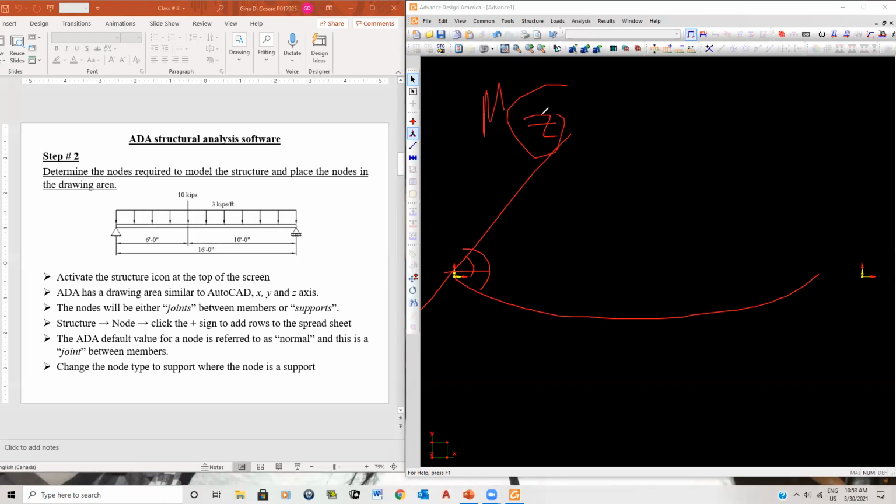If you were doing a three-dimensional analysis, then when you're in the other axis, you have to free it about the MX and the MY. Otherwise, if you leave those fixed, it will not change anything in your analysis. But to make sure that you've done it properly, you have to free it on the MZ, and that's why you still have the red dot. And I'm glad you had that mistake. That's a classic mistake everybody makes. They always use the wrong axes about which they have to be free. And if you're absolutely not sure, free MX, free MY, and free MZ. This way you won't have a problem. You understand? Okay, but that just takes a little bit more time.